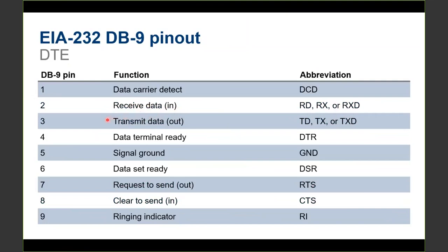We'd send out that request for data. We'd send the data out of the transmit port at the RTAC on pin 3. And if we follow that pin 3 right into the modem, you'll see that the transmit data coming into the modem is coming in on pin 3.